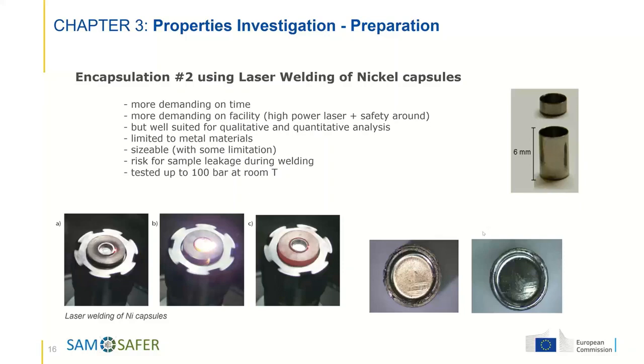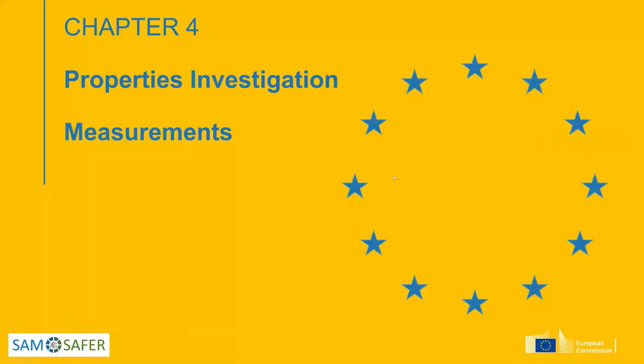The best is to heat it for several hours at high temperature and compare the weight before and after. That gives us a really good idea whether it evaporates or not, because if you go as high as 1200 degrees, for instance, you are sure that if there is leakage, it will decrease the weight. So let's go now to the experiments.